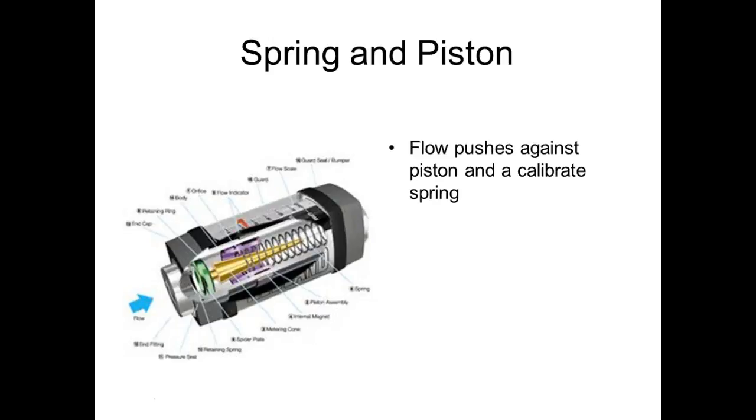So normally, in fact I think all of them, we work on creating a pressure drop. But it's not going to be very much. Over here we might have 100 psi, and over here we might have 95 psi, right? Anytime you send flow through an opposition, you lose pressure.